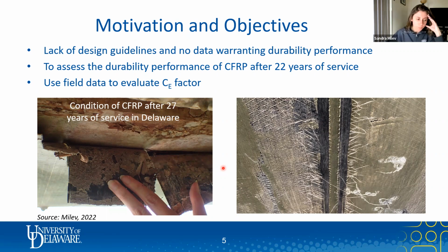Plus, the concrete on this bridge was really in a bad condition. There was a lot of corrosion and cracking, especially longitudinal cracks. So I think that also overloading of the girders may have caused some of these problems.